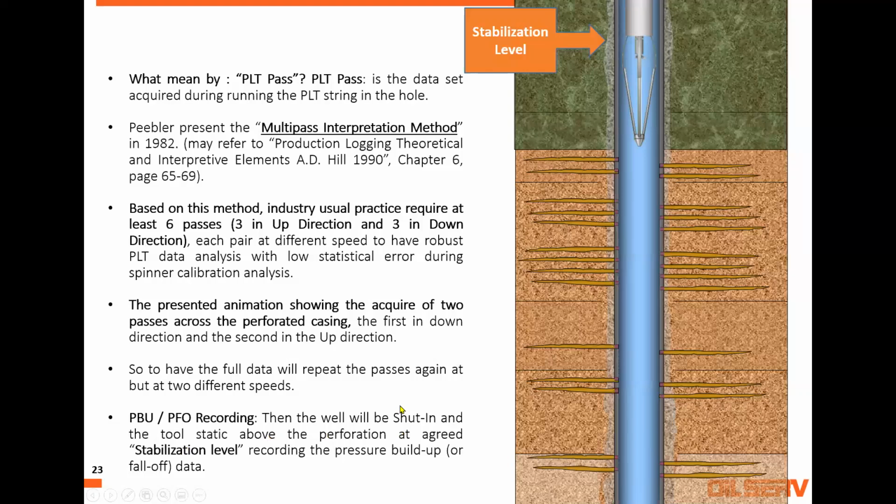Or in your case, as you mentioned, like viscous fluid, which is good. We have actually some viscous. I saw that in one of Amara field. When you put the spinner at the stabilization level, it is stuck. It does not rotate, it stops. Even at stabilization level while you're producing, you have to see on the logging screen that it keeps rotating, not stopping. So you need to go down a few times, clean it, then you record again.